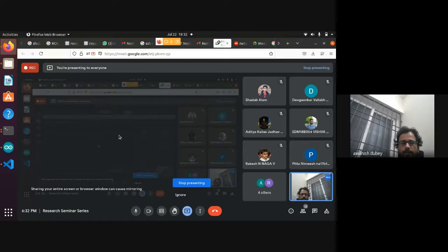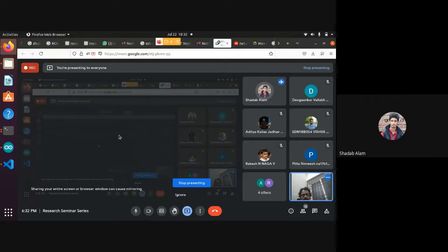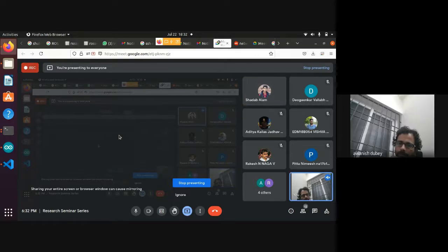Whereas on a wheeled robot, if my wheel has turned 360 degrees, I must have moved forward by 1 circumference of my wheel. Is that making sense? Yes, sir. Got it. So since that cannot be done here, the only way we get feedback is through the sensors, through the GPS system.